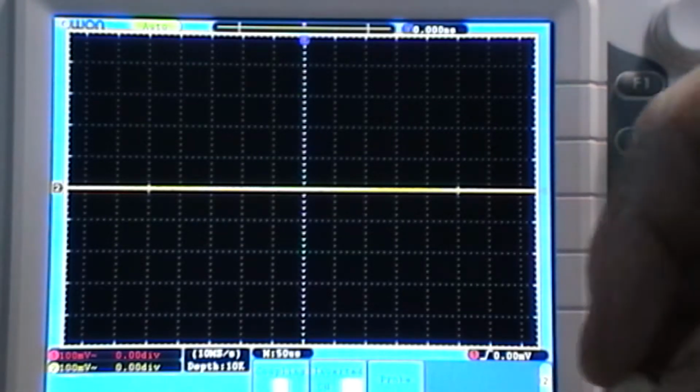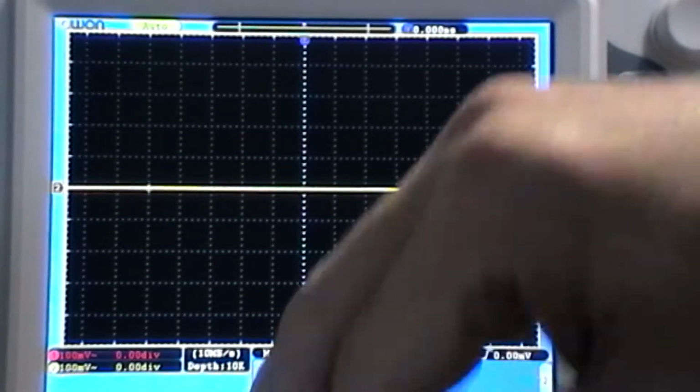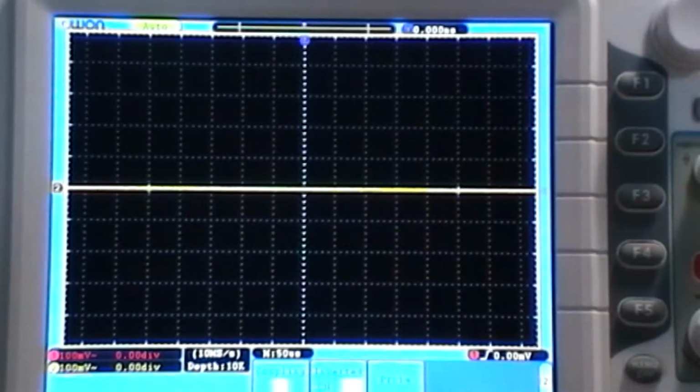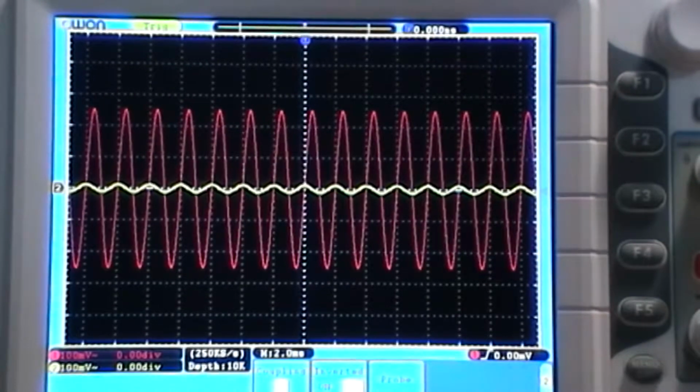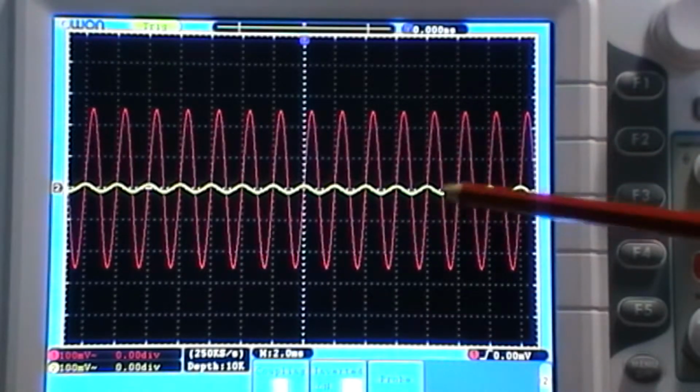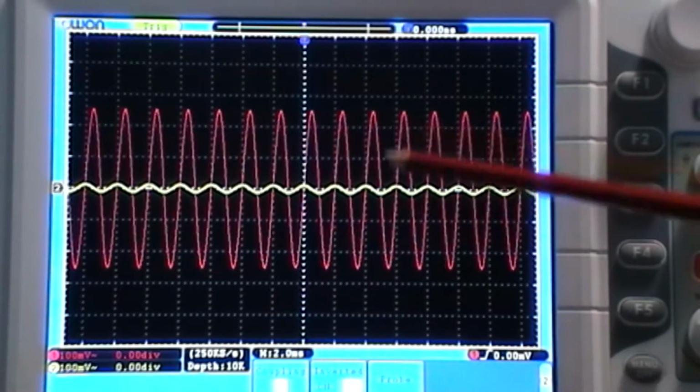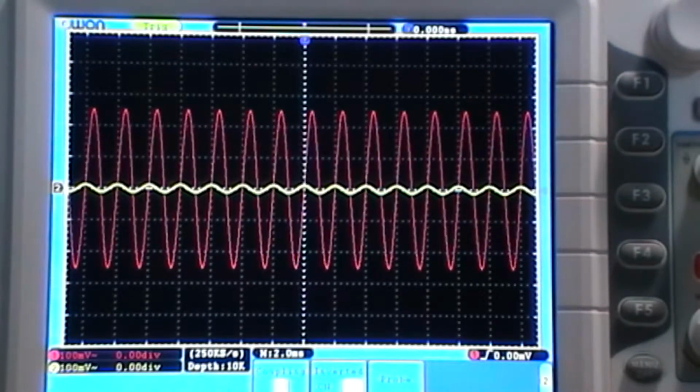Now I'm expecting with this, as I've calculated, that we're going to have a really high frequency cutoff point. So anything that's really low is not going to come through. So if I crank this all the way back down to the 500 hertz starting point, we are way below the cutoff point. So I'm expecting that at 500 hertz we will basically have nothing coming through. Just, yeah, you can see that we're already massively attenuating this, because my cutoff frequency is 10.6 kilohertz and we're at 500 hertz. So basically the low end signals, these low signals, are not going to come through.